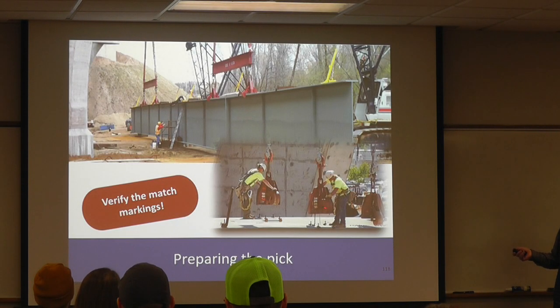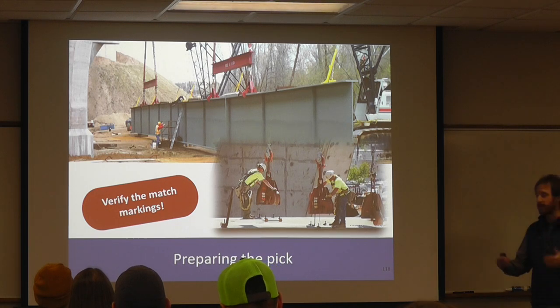You can see these are rather large lifting hooks, lifting devices. These are going to be in that erection plan. There's going to be a location for these. They can't just willy-nilly put them anywhere. It's something to kind of keep an eye on, right? Do you have to physically go up there and measure it? No, but it'd be nice to see if the iron worker's got a tape measure out or has painted a spot on the beam or something like that, right? Watch that. Look at the match markings while it's on the ground. Is this the piece that we thought it was going to be, right? Especially if trucks are coming out over it.